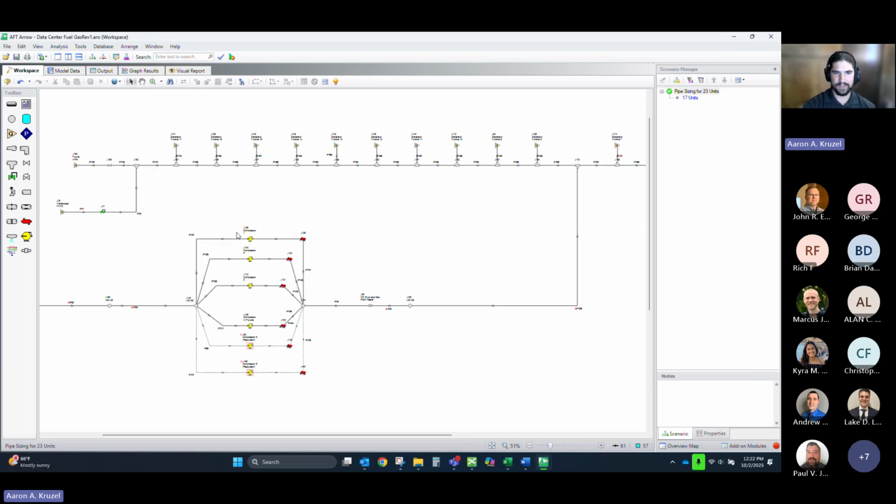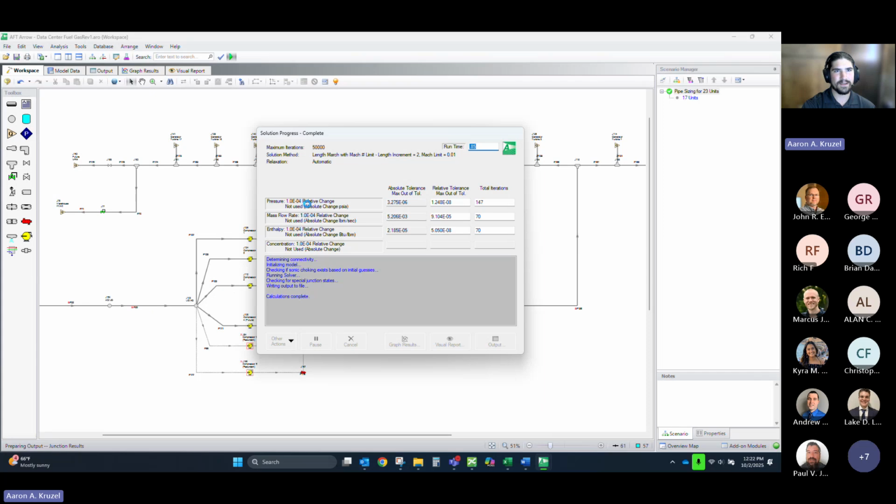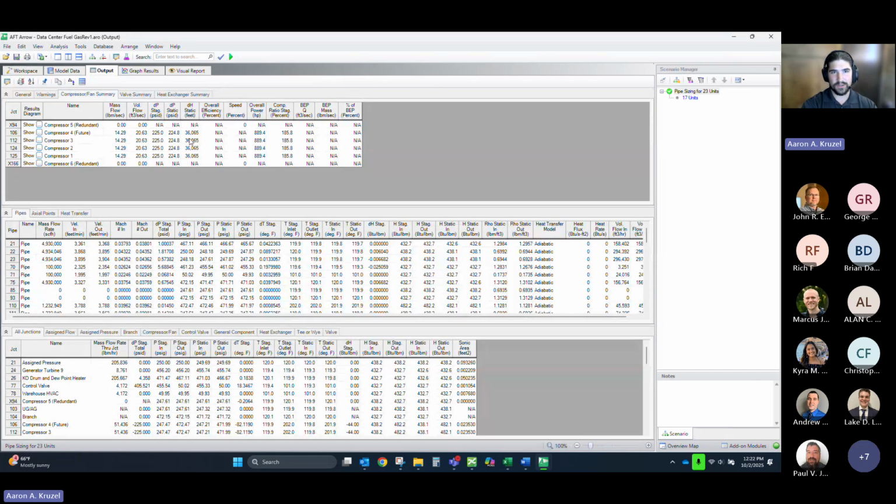For example, we have added compressors and heat exchangers to account for what we need to supply to the end user, and we've been able to send those out to our procurement specialists, and our procurement team can get started on this stuff, as well as electrical. So with our results, if you see them, we get some compressor results as well. In addition to sizing heaters, you can size other equipment like heat exchangers, compressors, any piece of equipment that's large enough, dew point heaters or knockout drums, stuff like that.